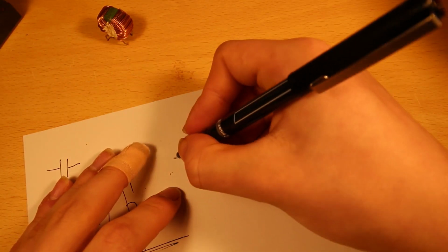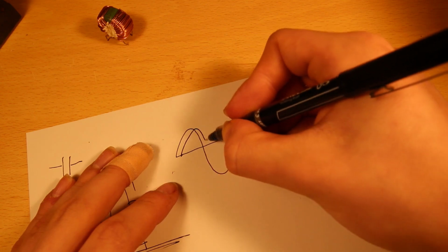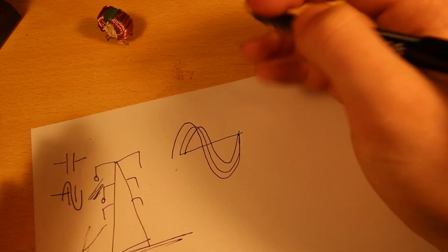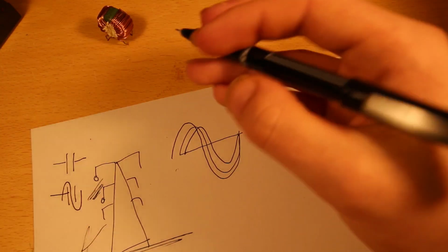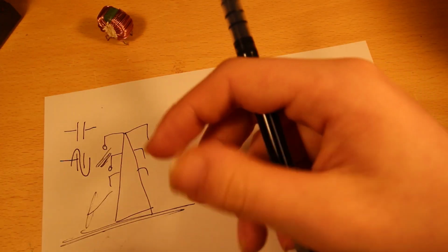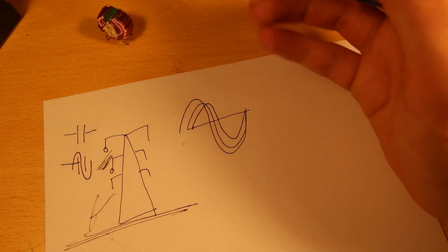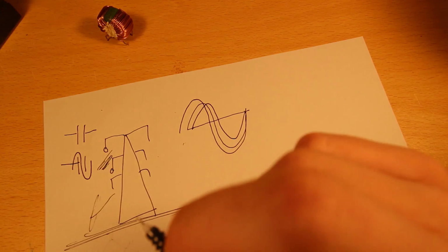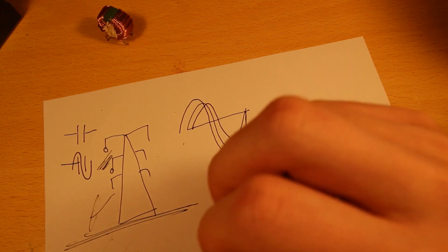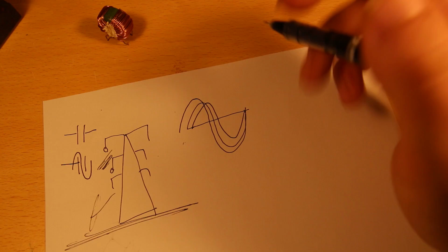The way it works is if you have an AC waveform like this, and say an inductive or capacitive load, the current waveform might look like this, or it might look like this, depending on what the load is. But that leading or lagging, at worst it will be 180 degrees out of phase. That leading or lagging causes the apparent power, which is the actual amps flowing through the cable, to be higher than the amount of current the load actually uses, which is the difference between apparent power and reactive power. This is getting very deep into very complicated theory I do not want to be explaining, but the simplest way to explain it is basically that's bad.